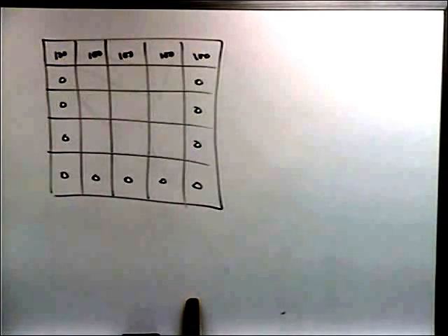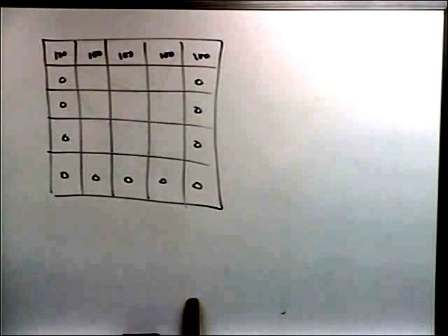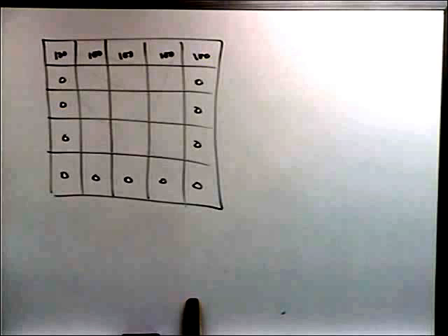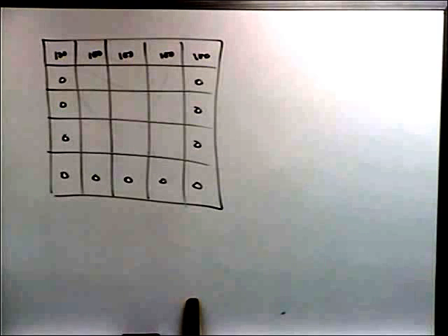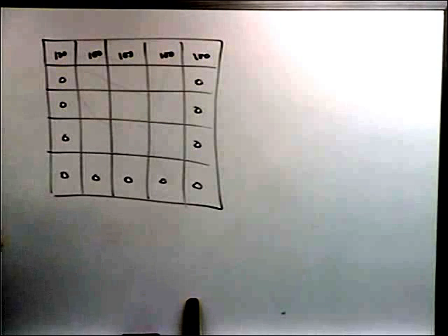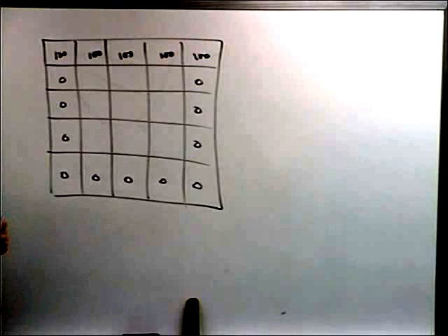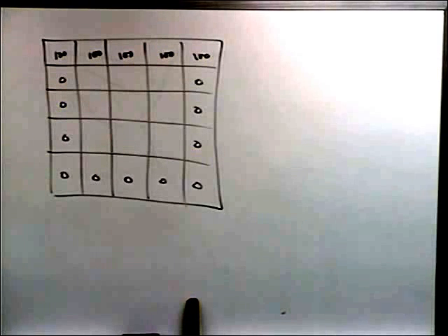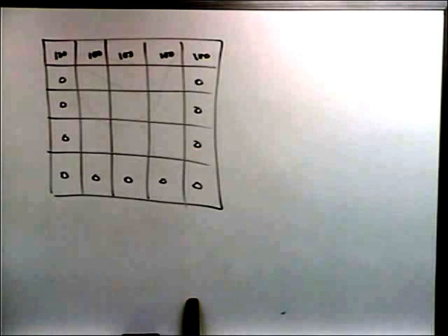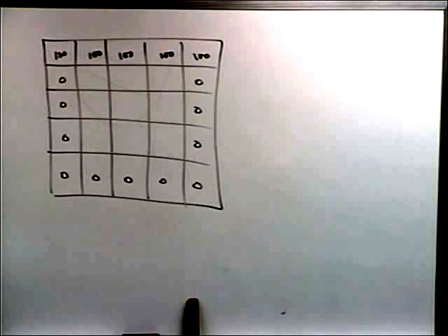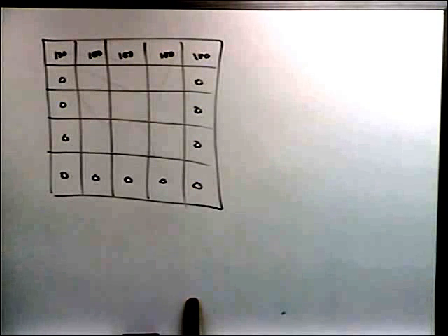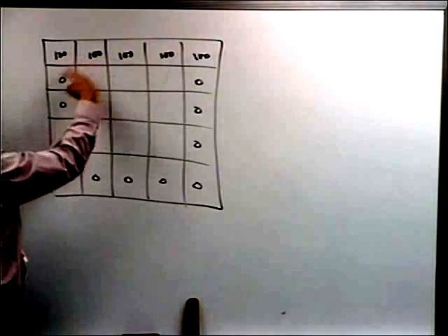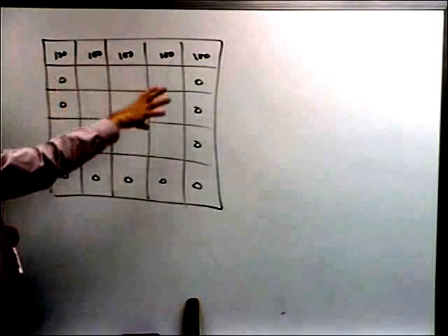Okay. Well, it just so happens that this is one of these numerical techniques that's always guaranteed to converge. There are techniques that go unstable and so on, but when you're solving Laplace's equation like this for these kind of boundary conditions, it always converges to the answer, doesn't oscillate or go unstable or anything. But if you were doing this by hand, you would go through, and at every node you would take the average of the other nodes.